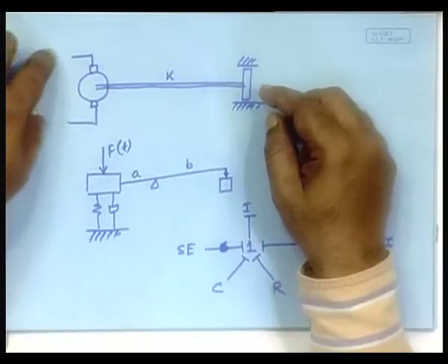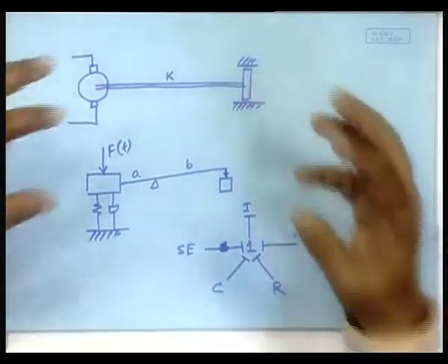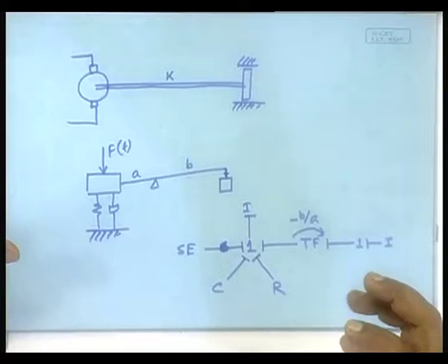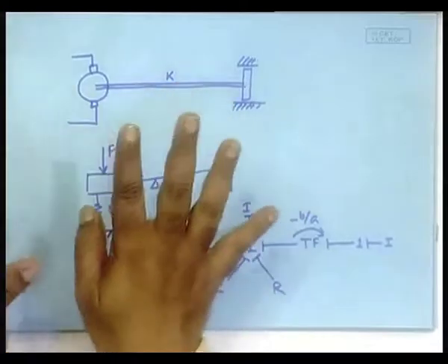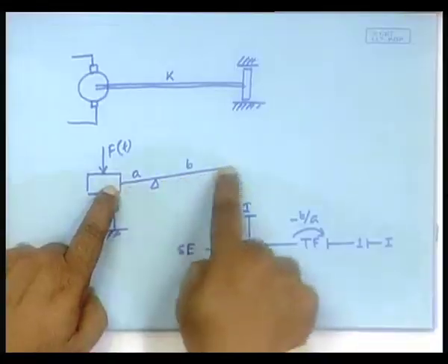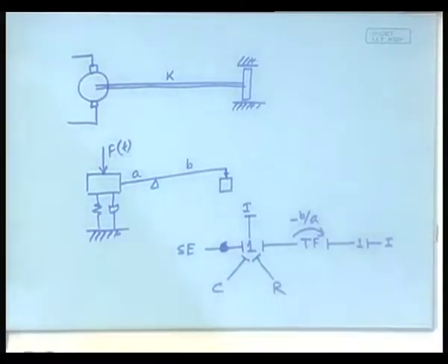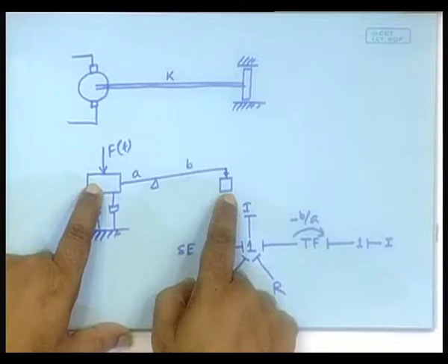which means that even though this and that or other elements in the system, for example, here there was an inductance, so there would be these inductances and the masses would have their own characteristic frequencies, while this shaft will have a very high characteristic frequency. So, they will tend to oscillate at quite different frequencies, right. Here also, if this fellow has a very rigid shaft, that means you will assume a capacitance here, but that capacitance will be set to a very high value, as a result of which this will tend to vibrate at a very high frequency, much higher than the characteristic frequency of the other elements.